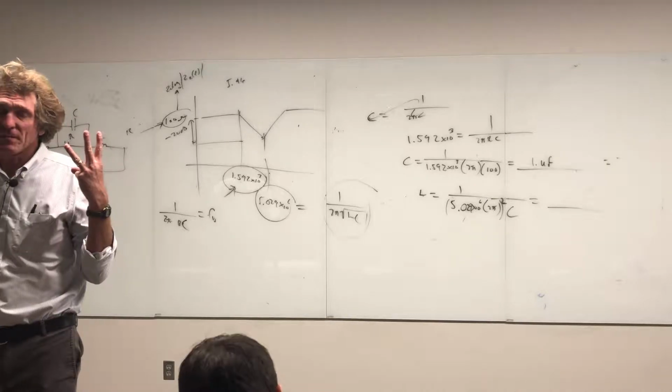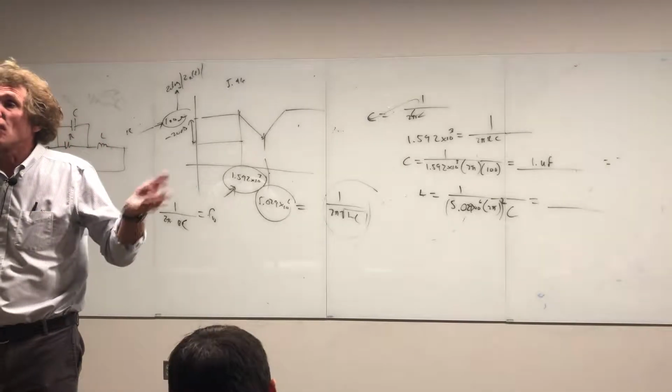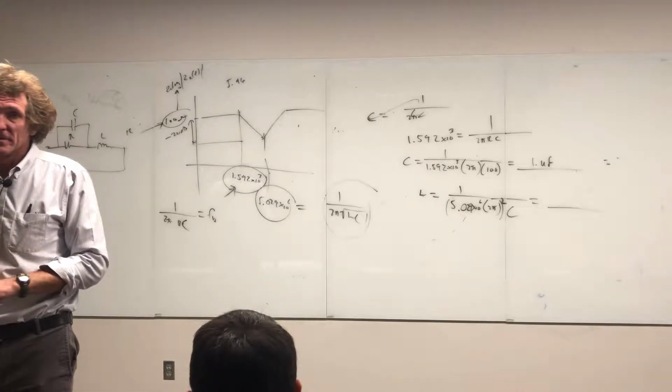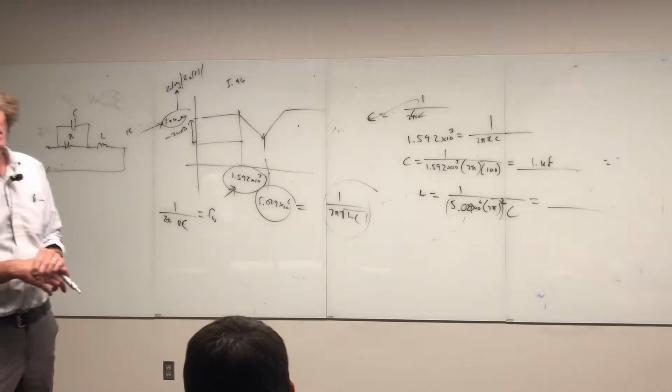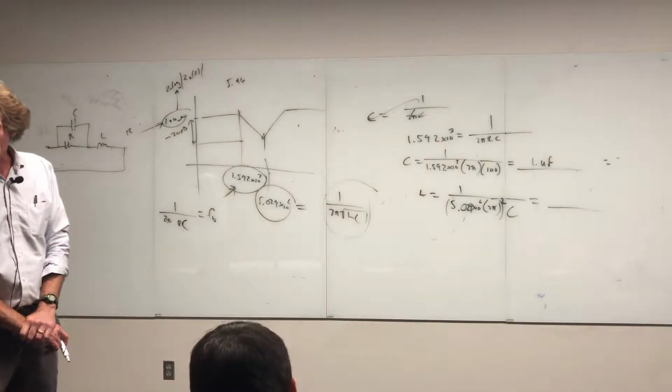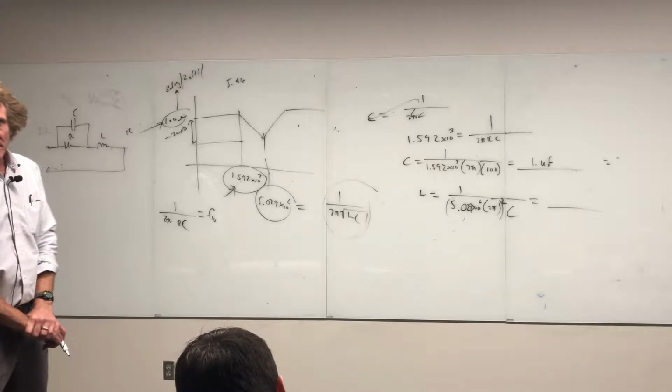The one thing about them all, at low frequencies, they all look like they should. And at high frequencies, they go bad, right? Inductors look like what? They should look like shorts. It should look like opens. They look like shorts because of the capacitance.